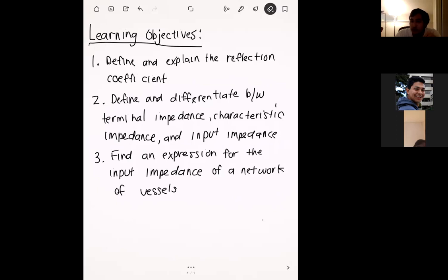A lot of software will define a kind of nebulous mesh quality, but sometimes it's not clear exactly what that means. Sometimes people just use the aspect ratio as mesh quality. Some people take the ratio of the biggest area to the smallest area or something like that. Some people take some kind of skewness metric too. So there are lots of different ways you can measure mesh quality, which I think complicates things quite a bit.